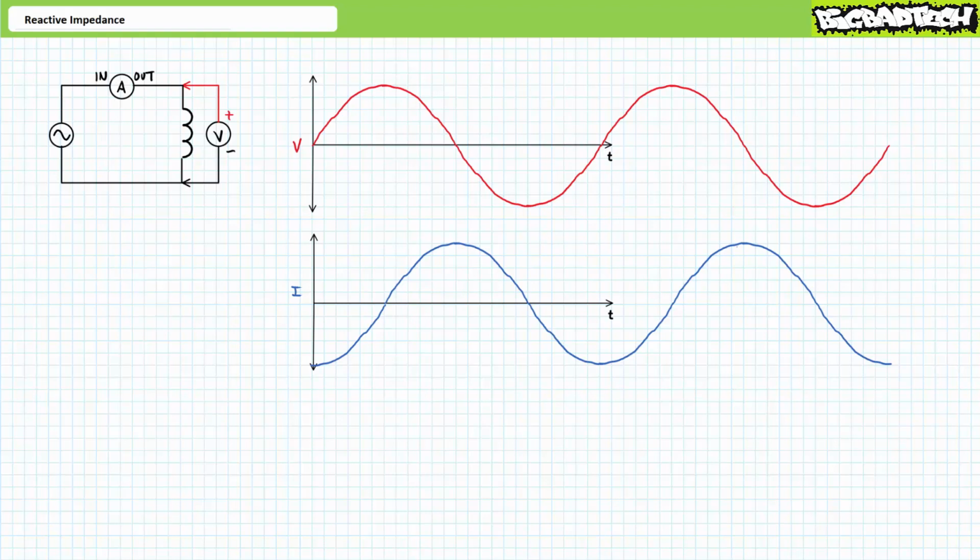Remember that AC waveforms are cyclical and repetitive. It really doesn't matter when or where we begin our analysis. I suggest we start here, where current is equal to 0. This choice of start point prevents the causality paradox I alluded to earlier. If we begin our analysis at any other time, the inductor already has some existing magnetic field. However, if we begin here, the inductor is empty and carrying no current and has no existing magnetic field. In short, it's best to start the analysis at an empty state.